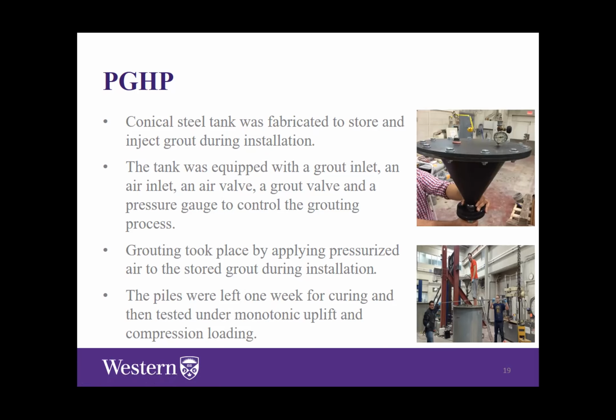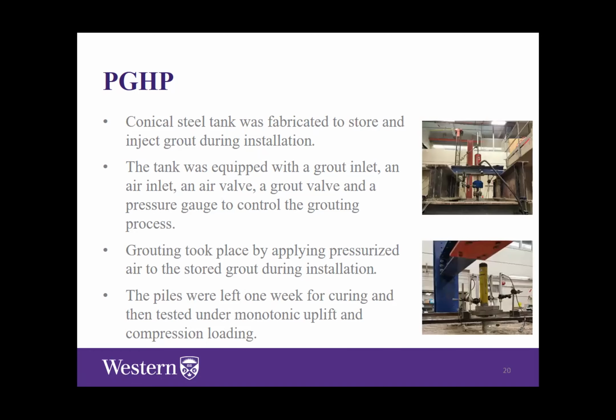We don't need to wait for another 3 weeks because we were expecting a geotechnical failure, not a structural failure. Then we tested the piles under uplift and compression loading to see the difference in performance between the conventional, or classical, helical pile and the pressure grouted helical pile.